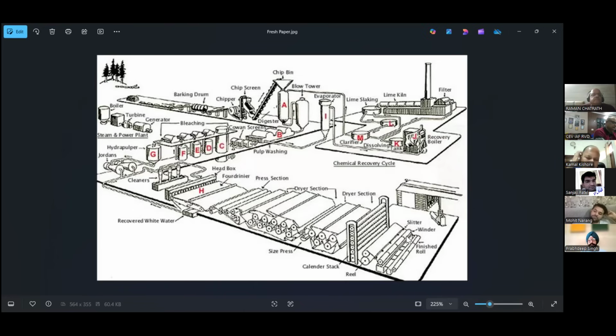And after the calendering machine, it will be wound up over the reel. And through the splitter, the large reel is cut down into small reels, just like a 3 meter sheet is cut into 1 meter 3 sets. So further, okay, this small paper roll will go for the cutting purpose, where it is cut down into the required size A0, A1, A2, A3, A4, and packed and goes for dispatch purpose or further production purpose.